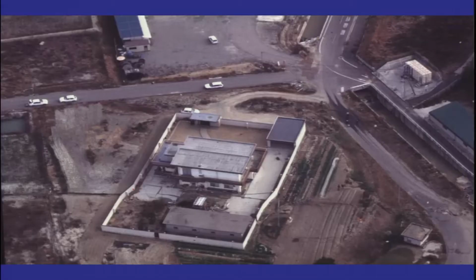So you can see the right lateral shift of this. It has been shifted like this, and similarly you can see the outer boundary which is coming. So the fault runs somewhere close to this, that is over here. If I precisely draw it on the scarp itself, it goes like this here. And the displacement is this block has moved in this direction, this has moved in this direction. So what we see here is the lateral movement along the strike of the fault, whereas the vertical displacement you can see in the next slide.